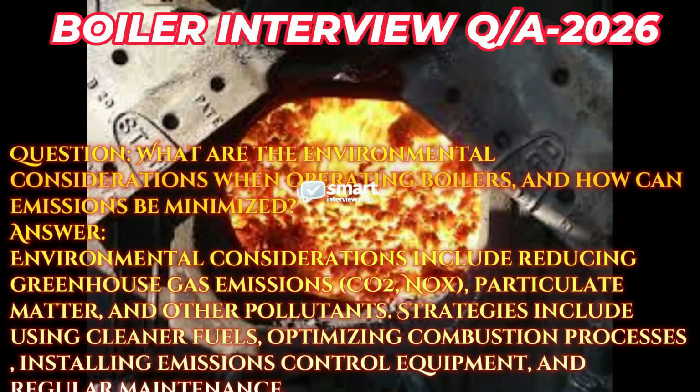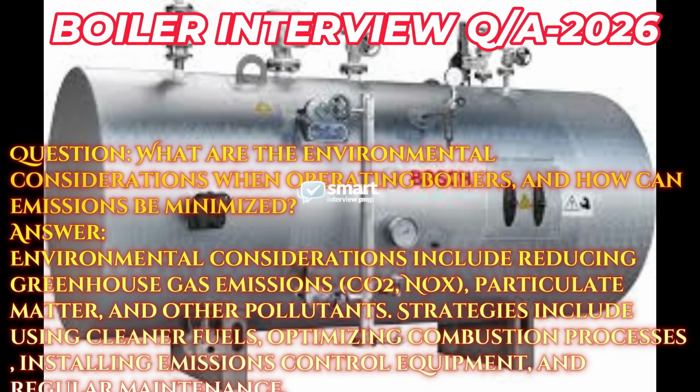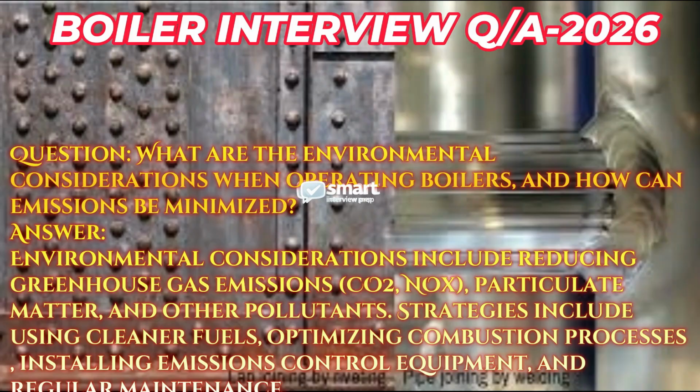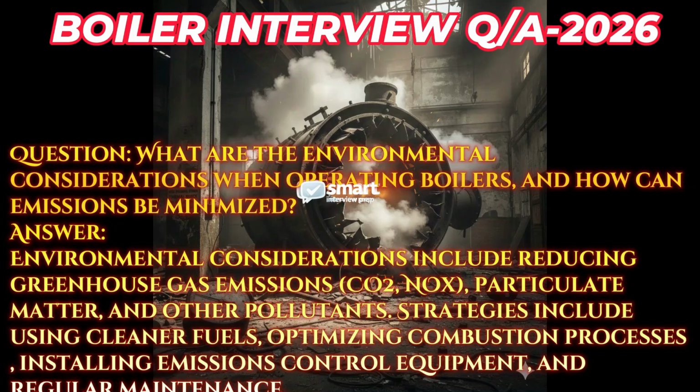Question: what are the environmental considerations when operating boilers, and how can emissions be minimized? Answer: environmental considerations include reducing greenhouse gas emissions, CO2, NOx, particulate matter, and other pollutants. Strategies include using cleaner fuels, optimizing combustion processes, installing emissions control equipment, and regular maintenance.